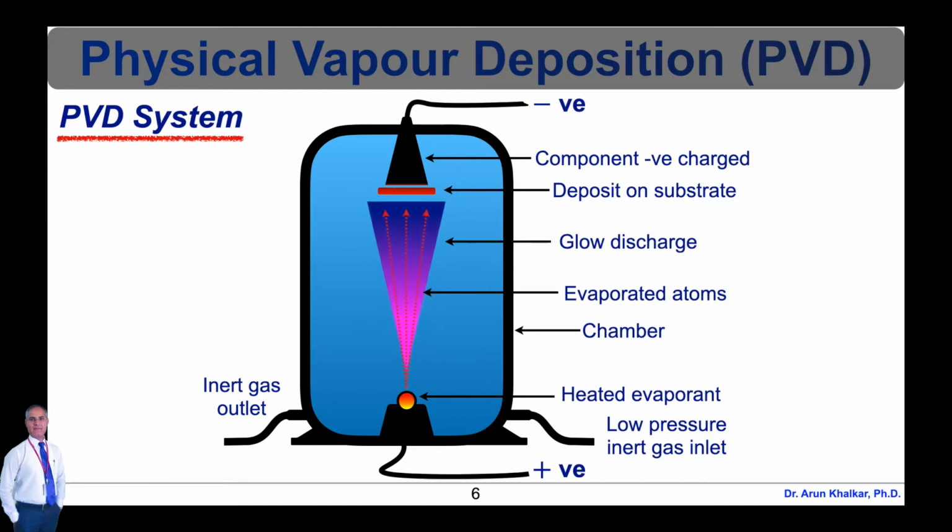The physical vapor deposition process generates a uniform layer on the substrate surface, from the nanoscale to the visible scale. This technique can be used to incorporate layers of almost all inorganic materials and even some organic materials. Less resistance is induced in the PVD processes, so through heterogeneous nucleation, a tight layer formation occurs with improved mechanical properties like hardness and wear resistance.